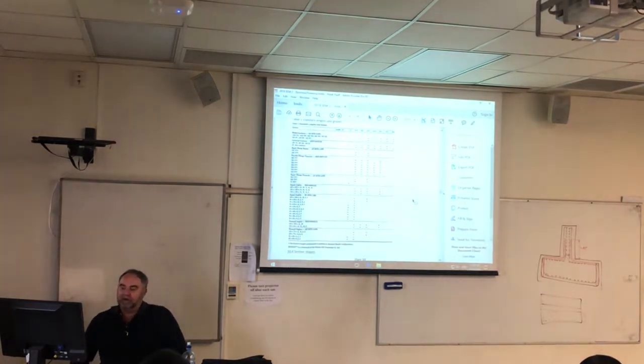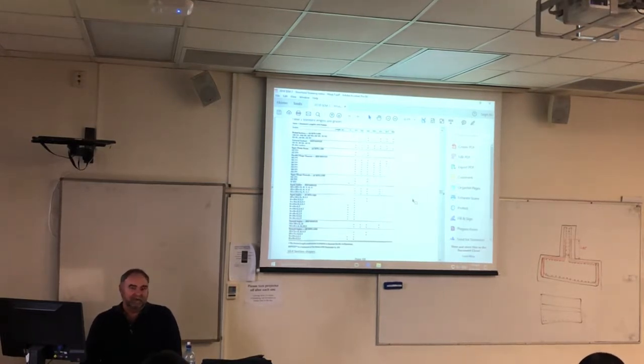Secondly, if you're looking for a note to do with the steel on the job, that's a very long piece of steel, 13.2 meters. You're going to need a big truck to carry that on site and a big crane to put it into place. So cost-wise, perhaps not the most effective way to do it, but at the end of the day, you've still got to draw it up like that.